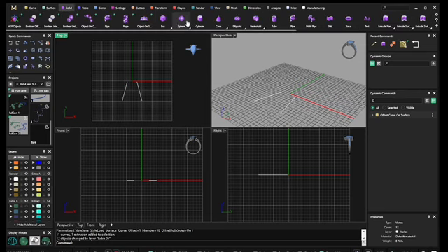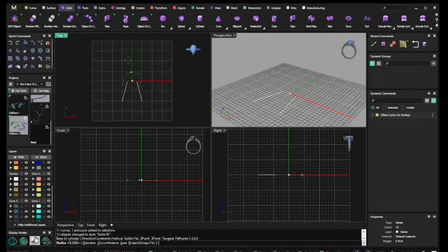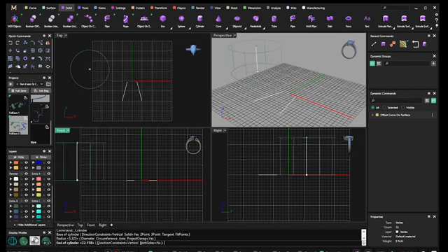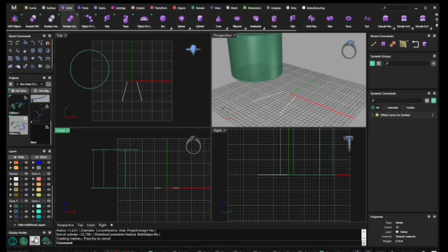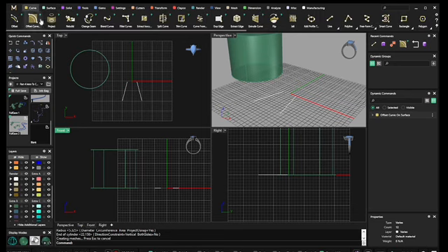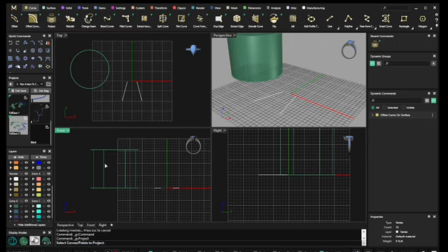I am bringing in a solid, and once again, I will talk about that a little bit more in depth later. But in order to do this particular action in the curve menu, I need a solid. This one is project, and it also is a dynamic command. I need to go to my line and create a line here.